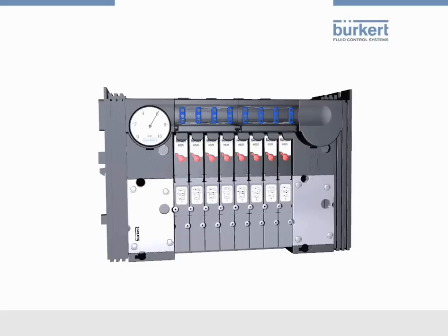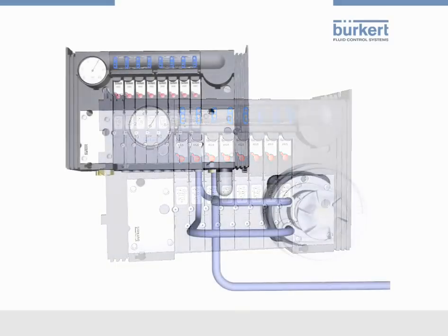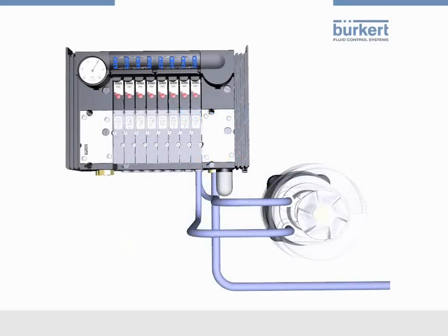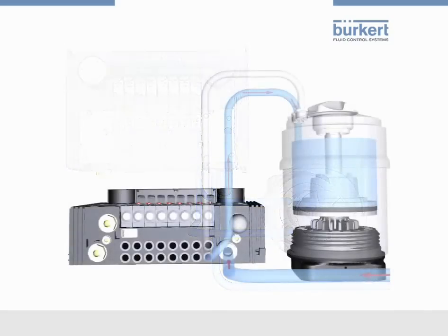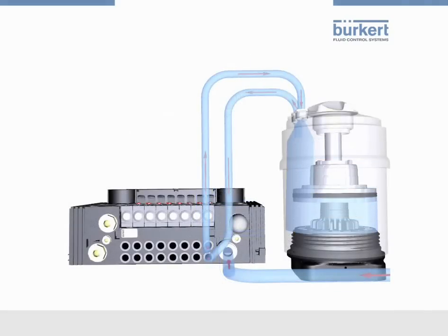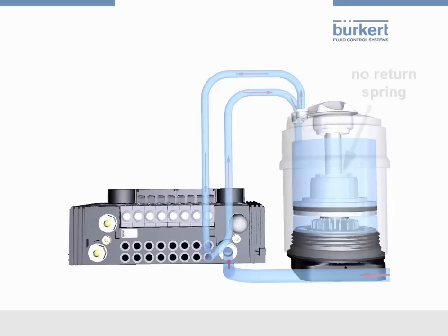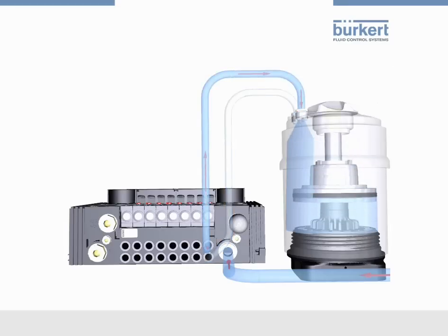In the 3D illustration of Type 8644, 5 two-way valves are incorporated and shown. As we've already learnt, a 5 two-way valve serves as a pilot for double-acting actuators. Now we look at how the combination with a double-acting element actuator works. In comparison to the previously seen Type 8640 with 3 two-way valves controlling a single-acting element actuator, here the return spring is missing. Both the resting position and the actuated position are operated by compressed air.